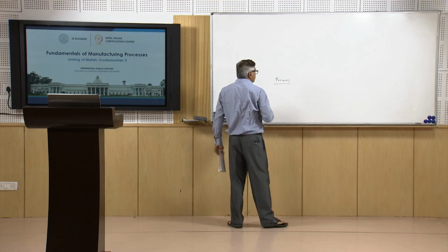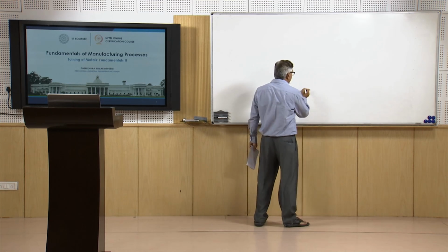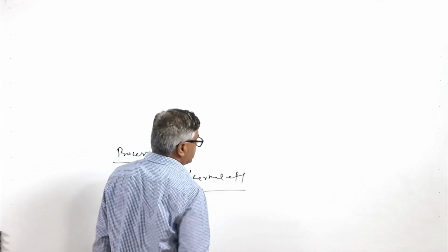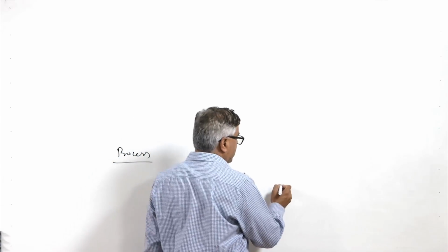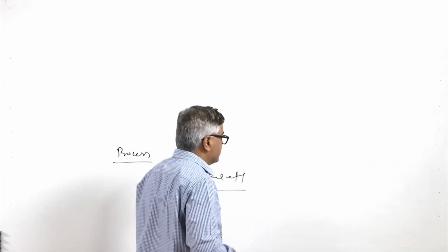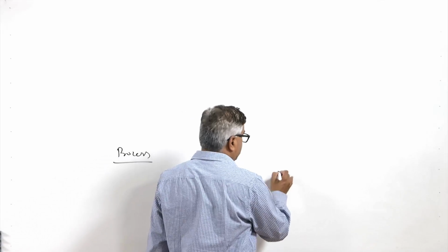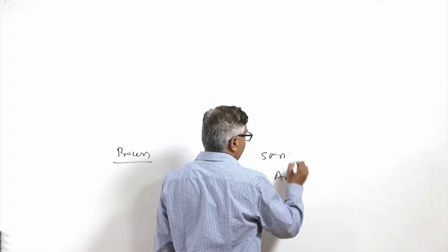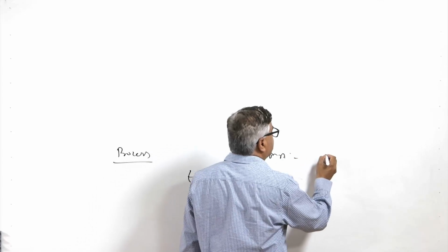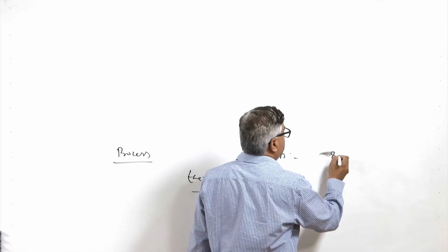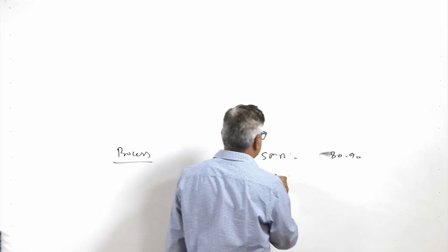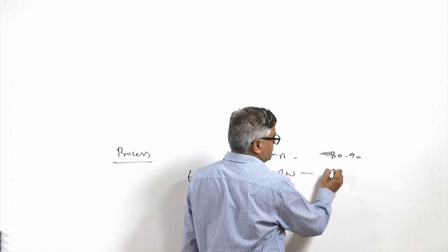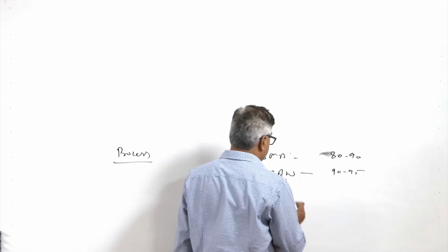Normally, if both are clubbed, we call it the thermal efficiency of the welding process, which is different for different processes. For simple shielded metal arc welding this may be 80 to 90%, but for submerged arc welding it is 90 to 95%.